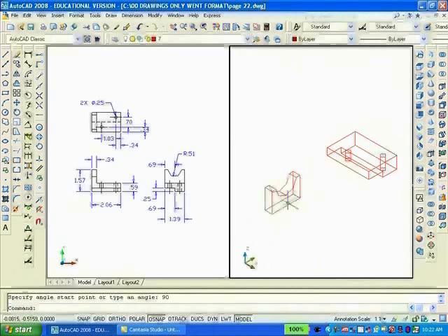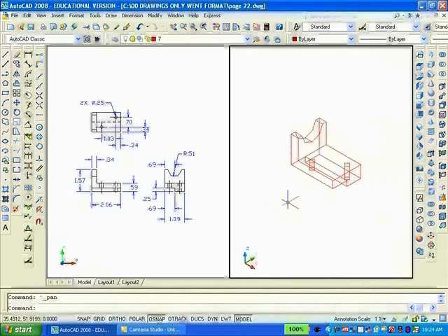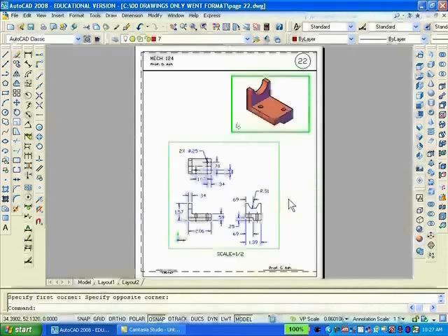And now I'll move that last part from its lower left-hand corner to the upper left-hand corner of the other part, and with the union command, make all the parts into a single object. When that is done, I'll shade the object and the solid is complete. Then I'll set up the two viewports as desired in Paperspace, freeze the viewports layer, and this drawing will be completed.